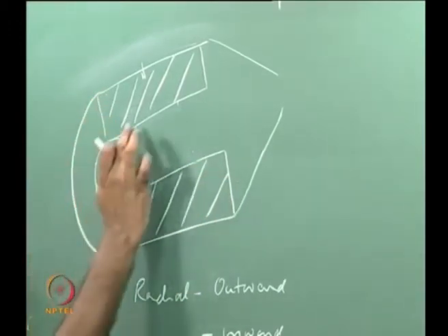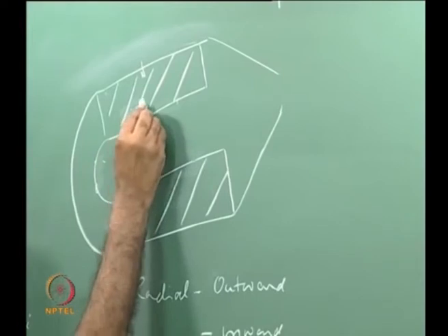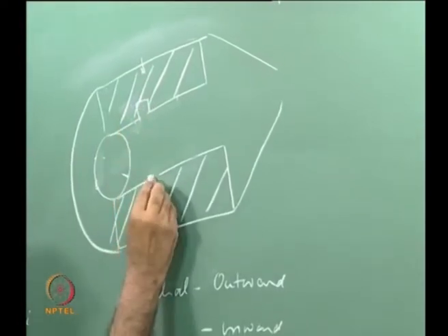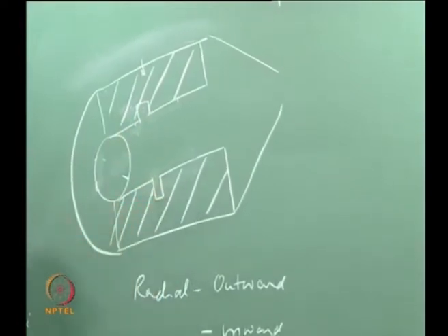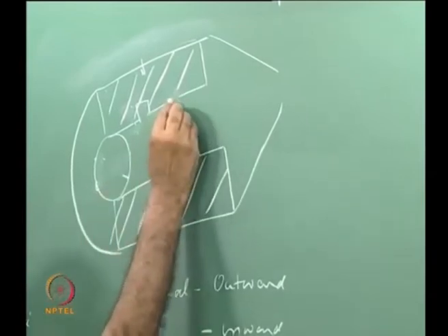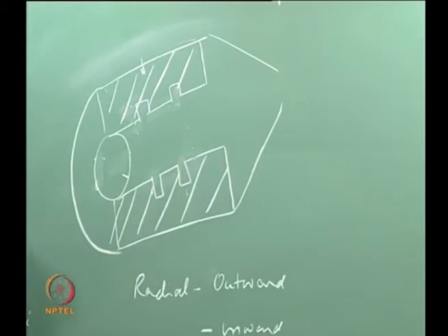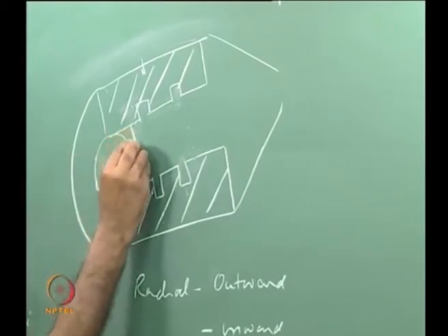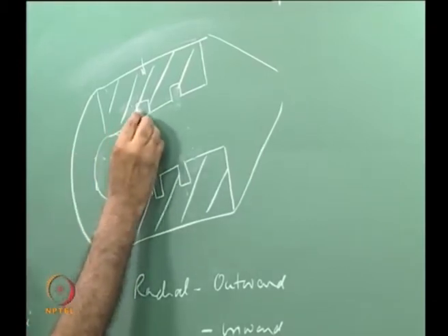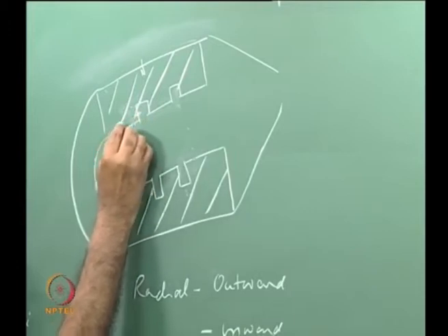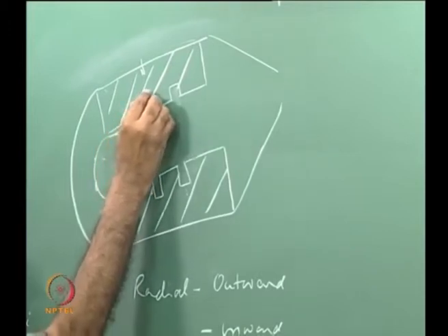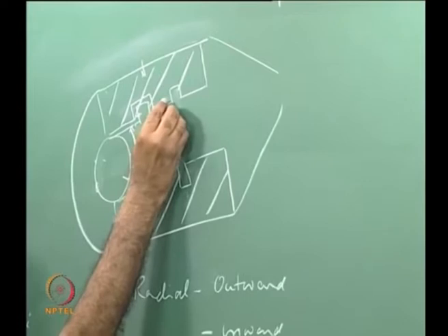The outer is the case, this is the grain, and now if I make some slots here, say I make a slot here, I make a keyhole here, something like this, then how is burning going to proceed? Burning goes radially here, burning goes axially here, that means at the next instant of time the surface is going to be something like this, coming over here.